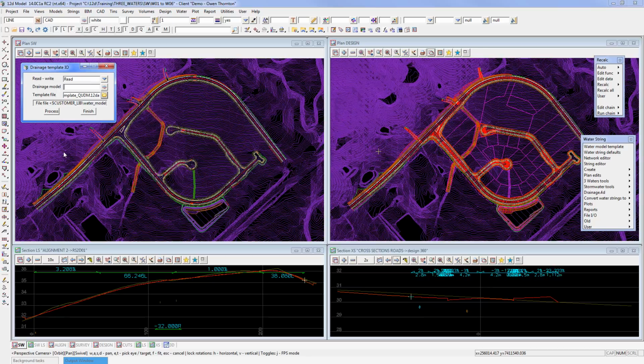All I really need to do to create my stormwater model is say I want to create a new stormwater model called SW, and if I want, I can add it to my stormwater view as well with the syntax comma SW, which is also my view name here, and it will add it in. And if I go ahead and hit process now, it doesn't look like anything's happened. So whilst this has just done probably more work than anything I've just been talking about in the last half hour, this little option here, it's really very simple to run.